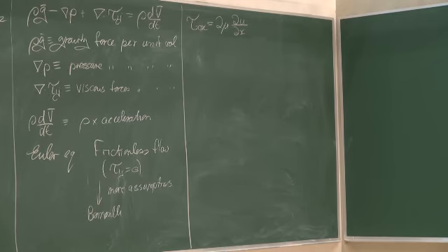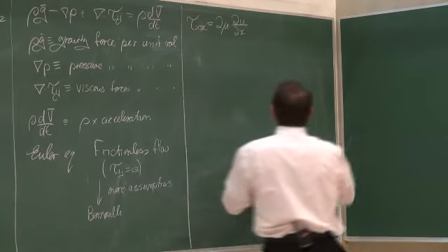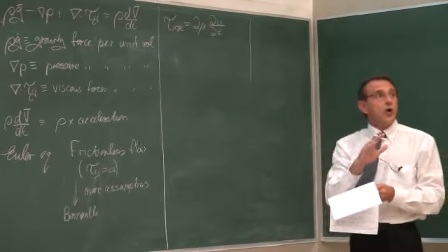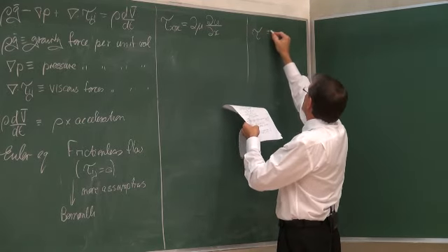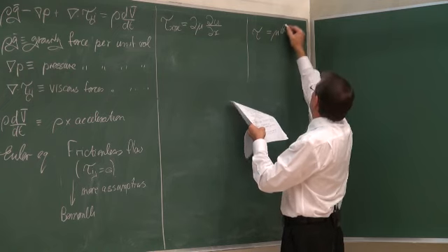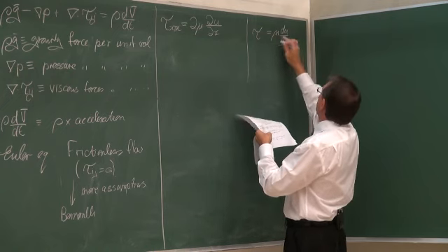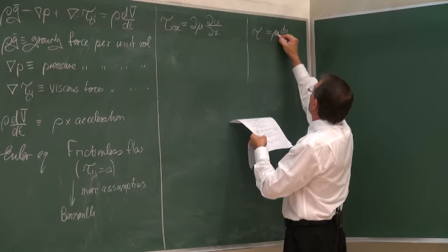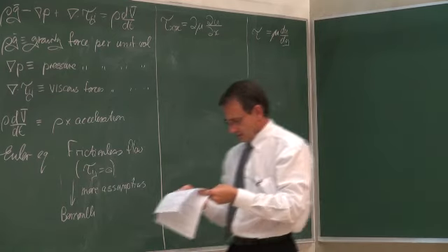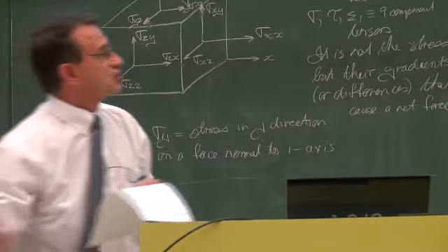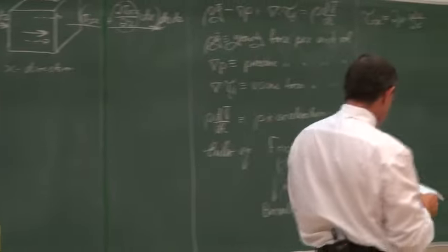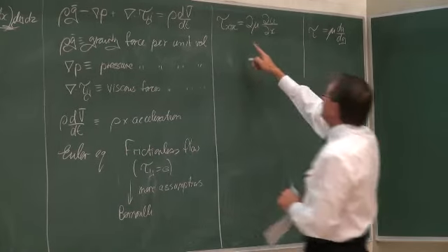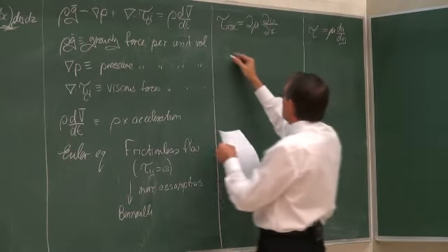Where does that come from? It comes from the fact that previously in White you've said that the viscous stress is equal to the viscosity multiplied by du/dy. Do you remember that? Okay, so there's a linear relationship between the stress and the gradient on a control volume. Now that would typically be for the tau xx term.